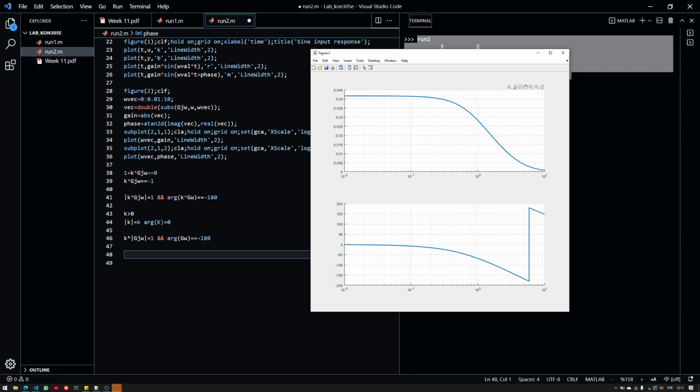for the gain, because that gain will help me out in determining the P-type controller that will match the value 1. So therefore, the method is pretty obvious. If you have a Bode plot, you look for the phase -180 degrees. The frequency at which this occurs, and then the frequency will be used to determine the gain that the system has naturally in it, and then you add a gain to it that will match the number 1 or the value 1 here. So then you can use that point.